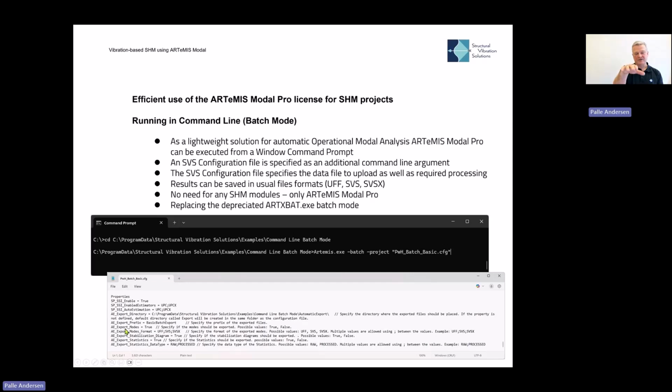Then all the settings that you have made in your signal processing are actually written into this section here, so that next time you open it, decimation and whatever it is has been configured the same way as the project where you actually exported this out from. So this is a way to put in the different settings, properties that are needed in order to do batch mode processing.